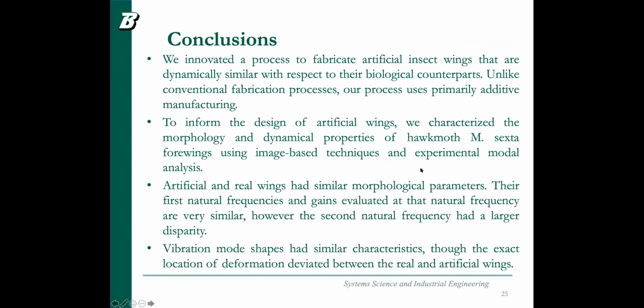So the conclusion here is we innovated a process to fabricate artificial insect wings that are dynamically similar to their biological wings. Different from conventional fabrication processes, like photolithography or laser cutting, our process primarily uses additive manufacturing combined with a heat molding process.